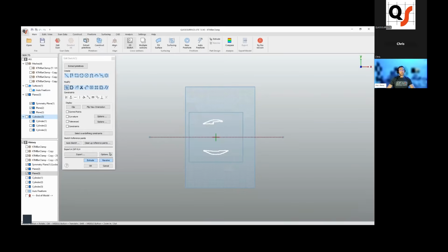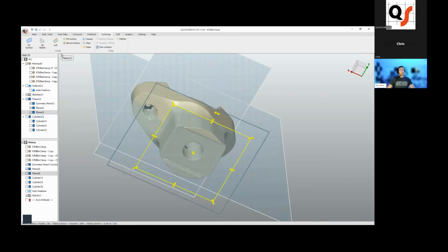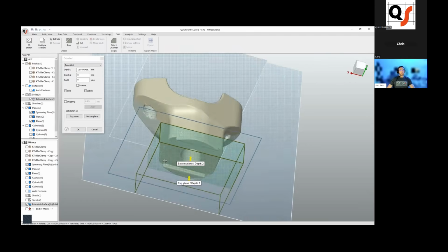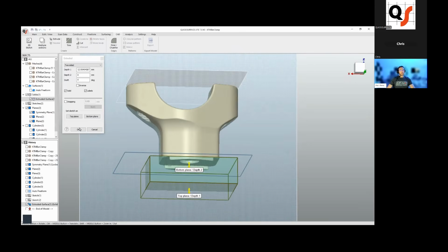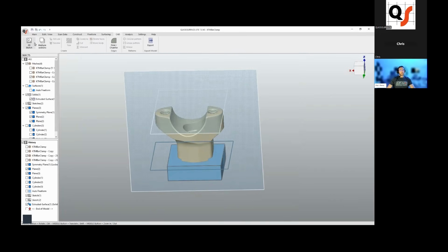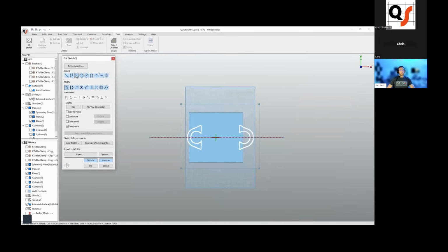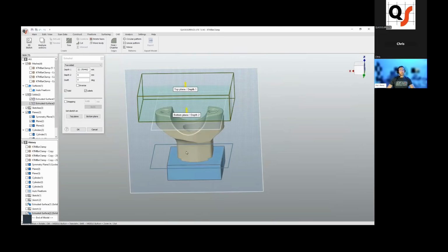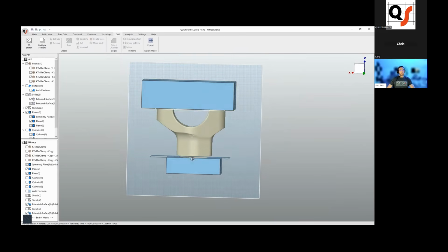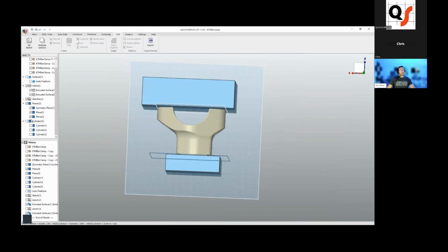And then we will create. And if you want to, you can just do things like create a rectangle. And I'm going to say OK. All right, so let's go ahead and turn this into a solid extrude. We'll say OK. And then we'll repeat that over here. So pick, top, create. We'll just make a big rectangle. And we'll extrude that as a solid. All right, so now when we export the solid bodies, those will go with them as solids.